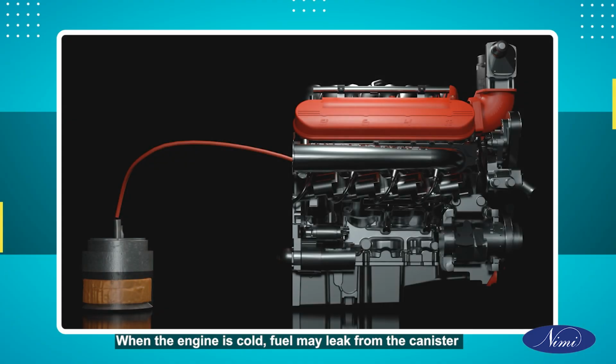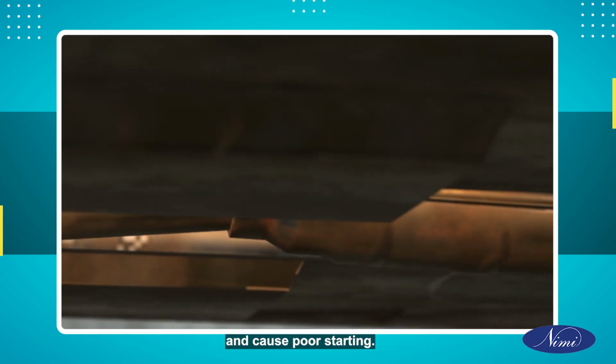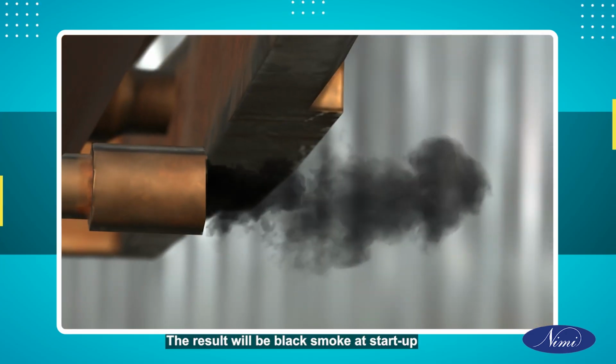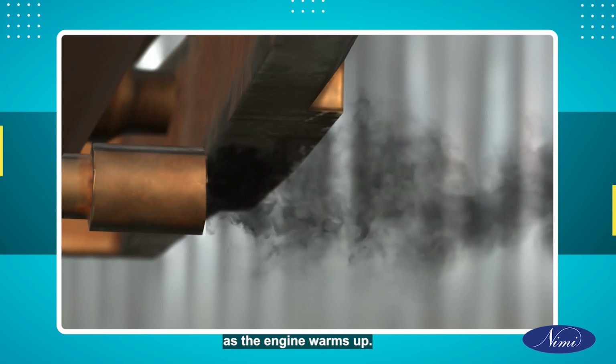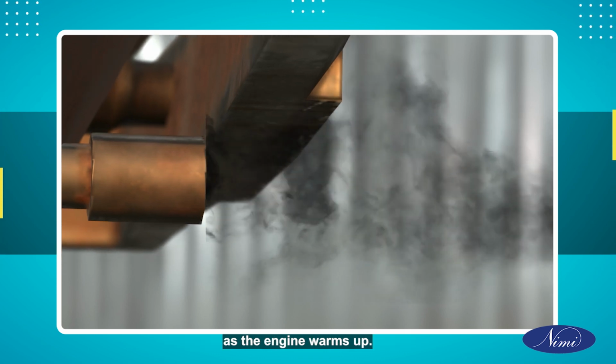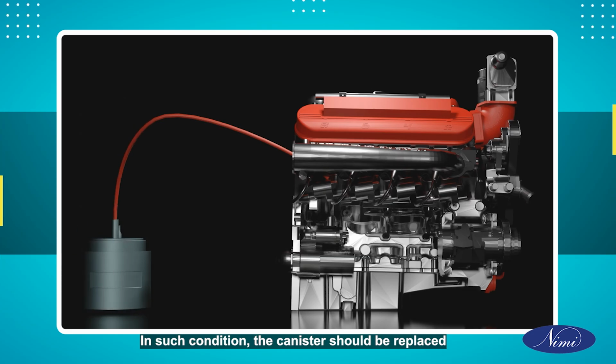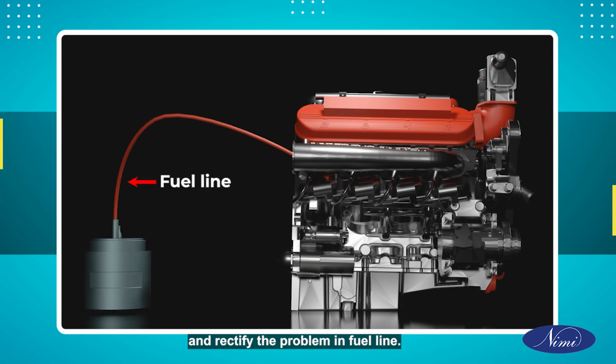When the engine is cold, fuel may leak from the canister and cause poor starting. The result will be black smoke at startup as the engine warms up. In such a condition, the canister should be replaced and the problem in the fuel line rectified.